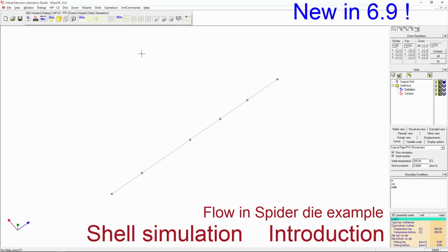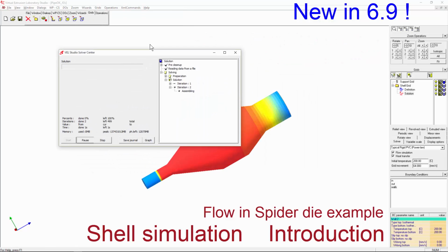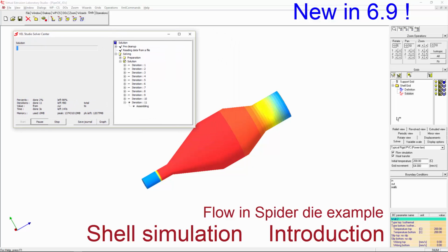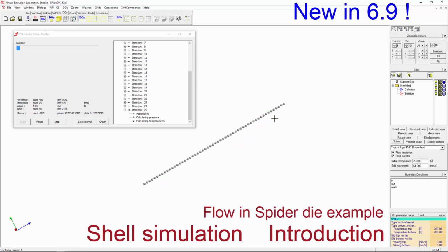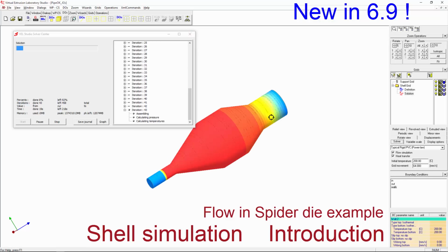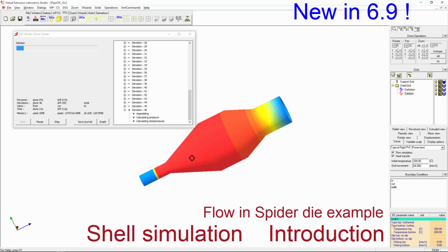Okay. Now, when you just click solve, the mesh is generated right now, and now this calculation starts. If I show you the real generated mesh, these are the shell elements being used. So you see they are much denser than the definition mesh, but they again are lines with certain parameters, and we only visualize those parameters like this, like a regular real die.